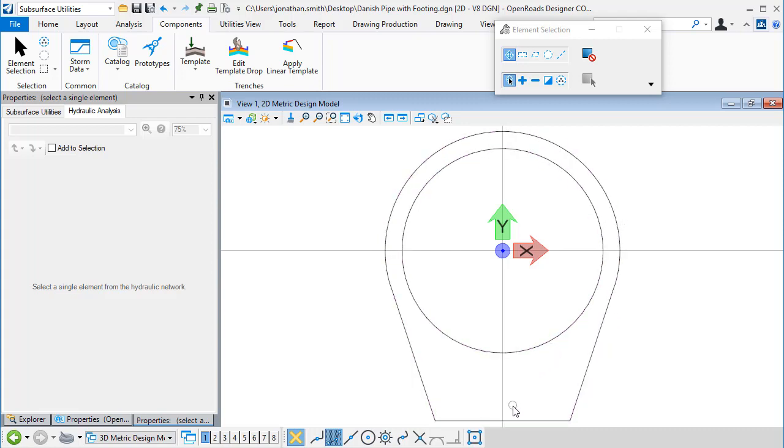But then down at the bottom here, you can see that the conduit wall is actually finishing with a concrete base or footing, if you like, which is horizontal. So we need to create the trench template using these graphics and then use that trench template in a feature definition so that we see the template appear in the 3D model.